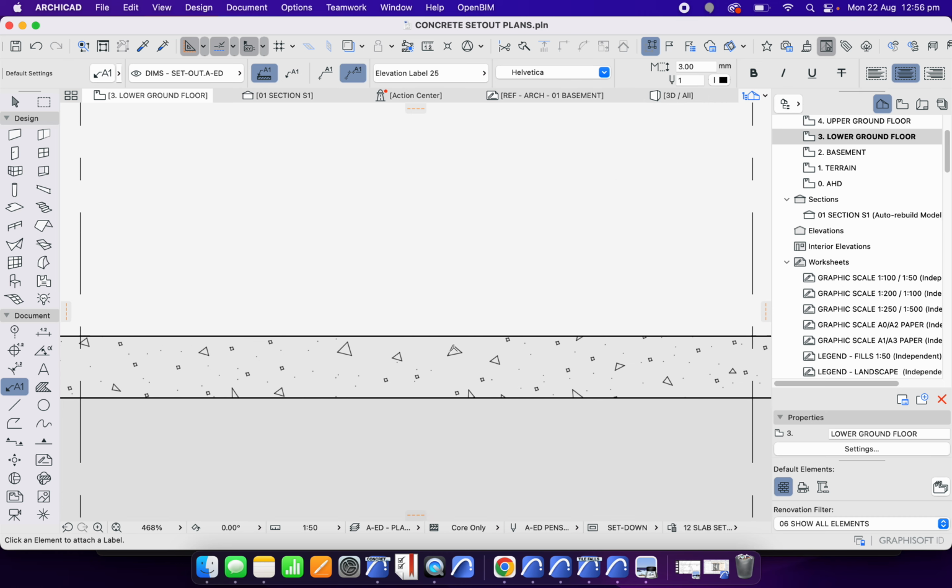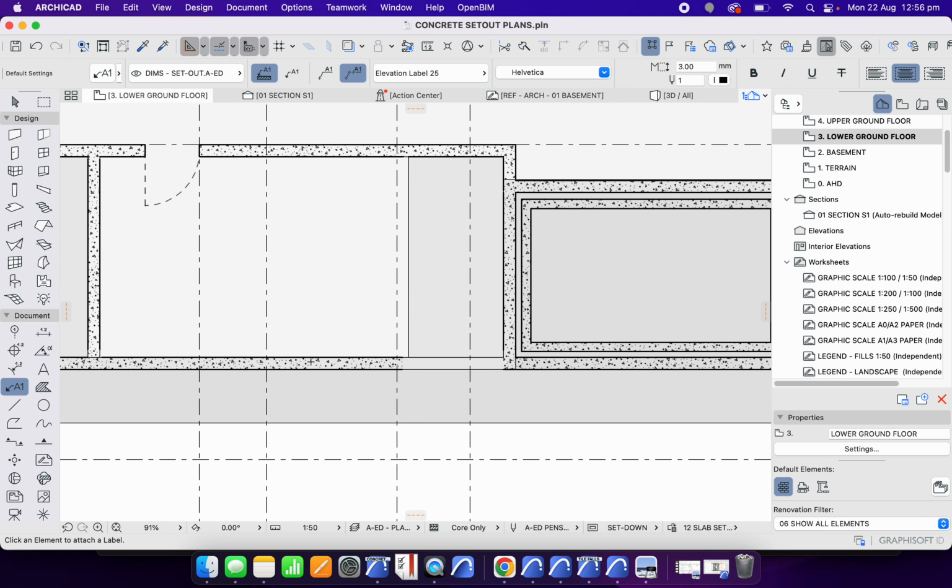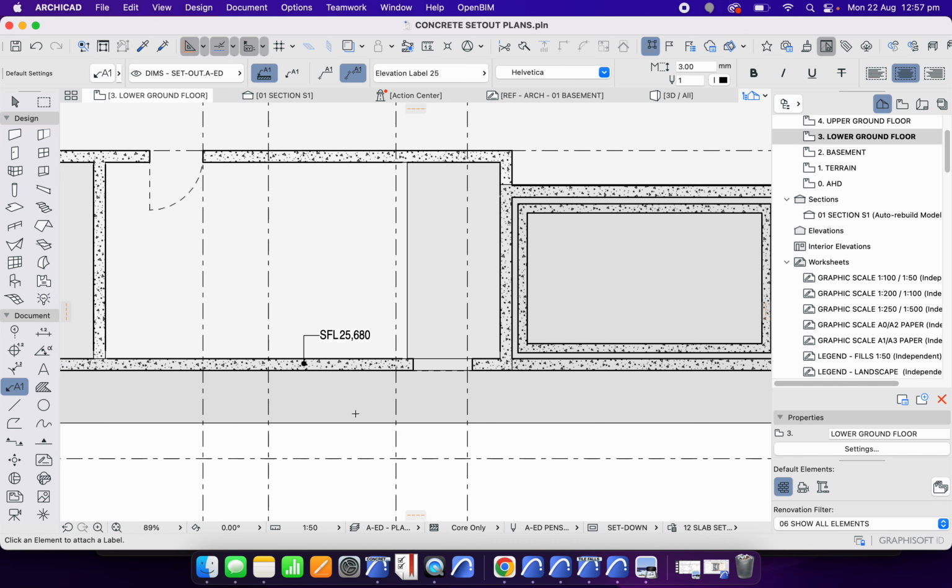So we'll put it over here. I need to hover for a second because I need to make sure I'm on the right thing. So when I hover, we can see that I'm on the wall at the moment. That's not going to work. So I need to hold or click tab, and we can see that's now adjusted. So I'm showing my slab, and then I can draw, and therefore I'm representing.